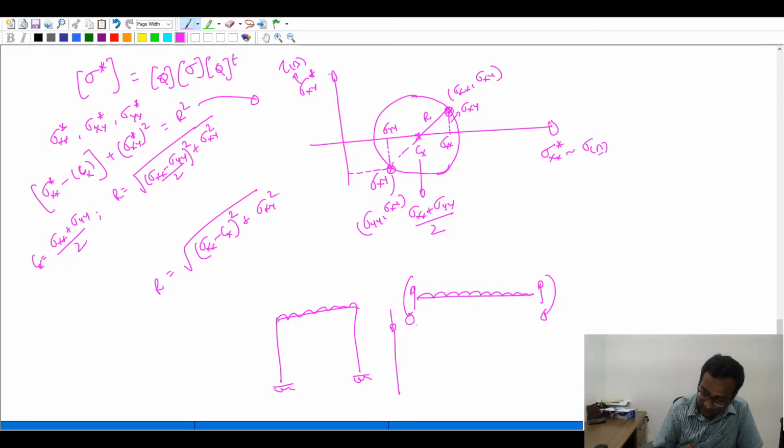and this is an anti-clockwise moment, so the moment here is going to be clockwise, and there can be a shear force on the beam, which will be taken as the axial force in the column, and the shear force in the column will be taken as the axial force in the beam. Okay, so there will be axial forces in a frame structure, just like our arch resists the upright moments only through development of axial force. A frame also will resist part of the forces through axial force.